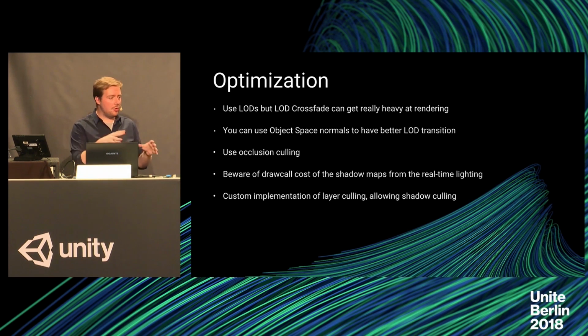We had a lot of small grass patches, like thousands of them on a small part of the terrain, and I basically created very large grass patches. So instead of having hundreds of them, I would have 20 of them on the ground. It has some downsides also, because since you have these really large grass patches, it's really hard to place them precisely. So it will clip with rocks on the ground, for example.